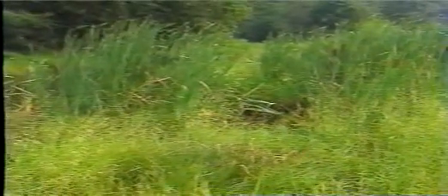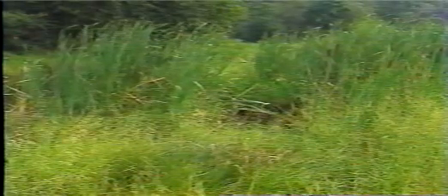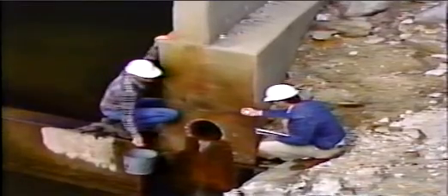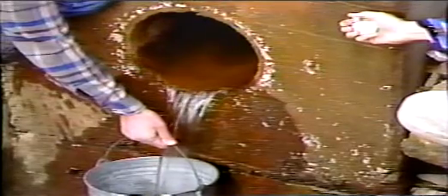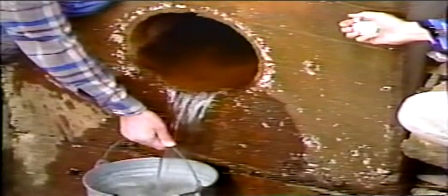Their presence may also indicate piping, particularly if a cone of material forms around the boil. Report sand boils immediately. Lush or water-loving vegetation downstream from the toe may be another indication of seepage. Check areas of lush vegetation for seepage and note their locations. Also, flow from toe drains and relief wells provides information on seepage conditions. Check the amount of flow to see if it is different than it had been previously for similar reservoir levels.